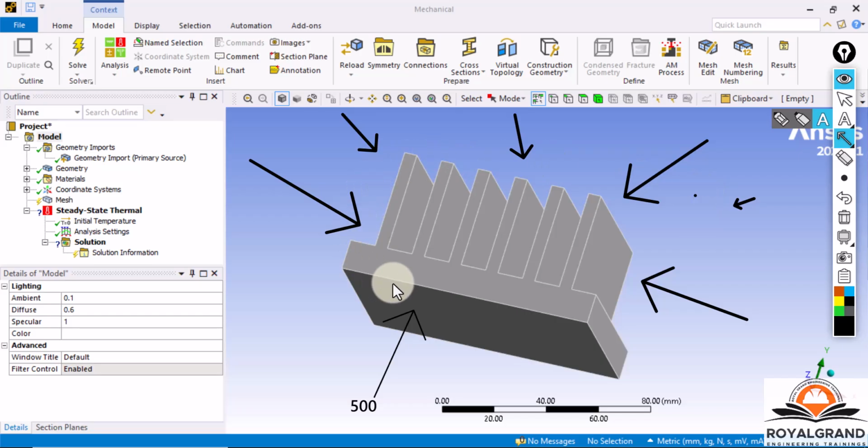And remember, from our definition, steady state thermal analysis analyzes temperature distribution and heat transfer in a system under constant thermal load. So this load will be constant, it doesn't change over time, and we use it to determine the temperature distribution. This is the thermal stress value over this body. You can also determine the heat flux using this constant thermal load, the 500 to 800 degree heat source and the 20 to 25 degree convection current.